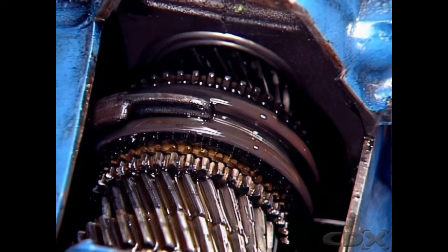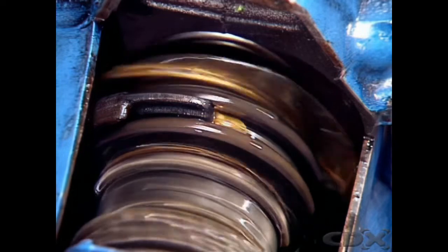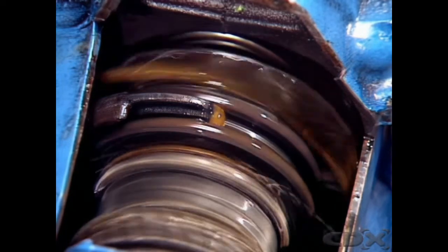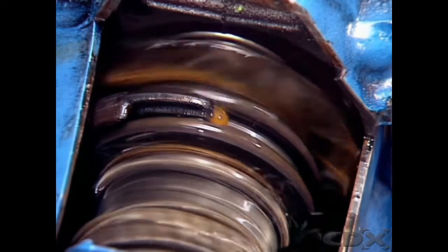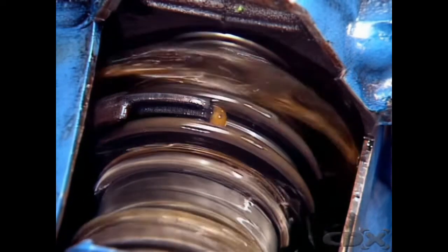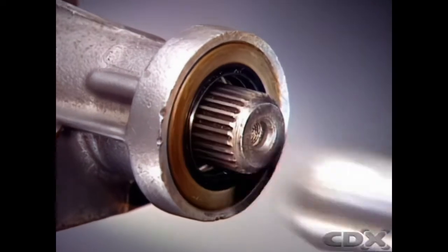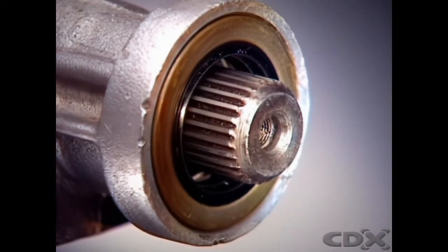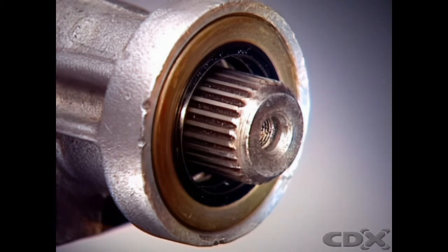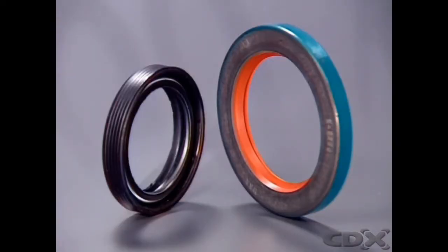The bearings can be lubricated by being submerged in gear oil or by oil splashed about inside the casing. Where the shafts extend from the casing, oil seals prevent oil leakage and the ingress of dirt and moisture. Garter spring lip type seals are normally used. They can be single or double lipped, depending on the application.